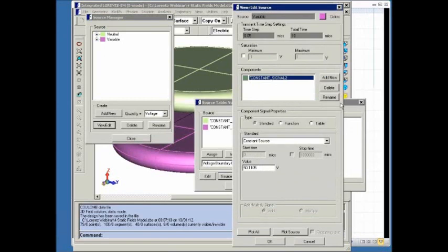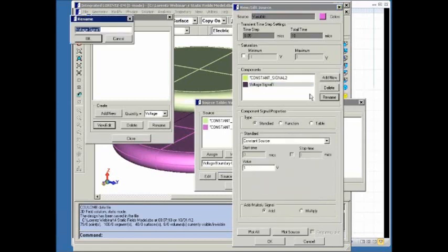There are different ways of doing that. One way would be to add a step function which has the opposite polarity. So I'm just going to copy this value, and then I'm going to add a new time signal, which I will call minus step at 5 microseconds.